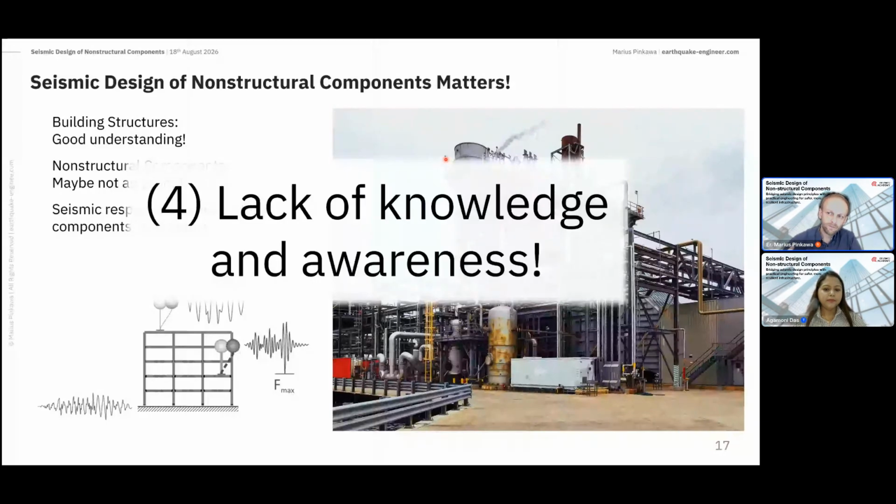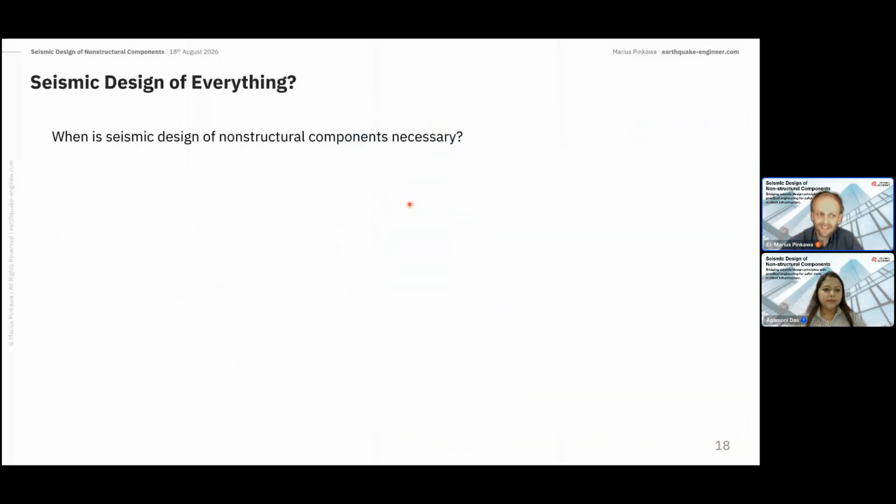So a very frequent question in my projects is, do we need to do seismic design of non-structural components? So is it necessary? There is a key question you can ask yourself to answer this. Can damage to a non-structural component, the first one, harm people? So can it harm people? If yes, you need to do seismic design.